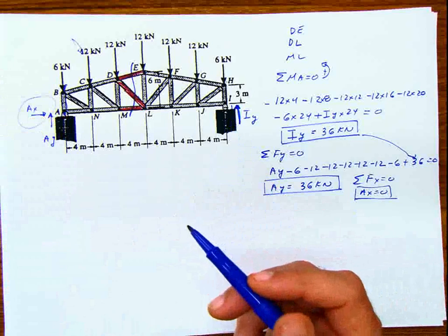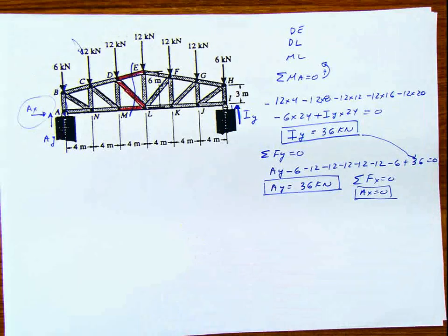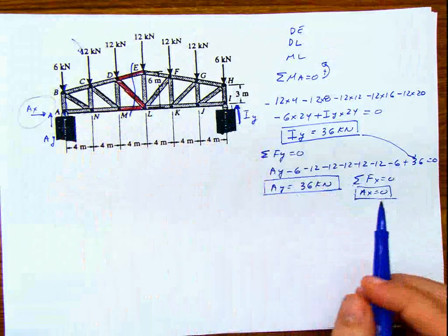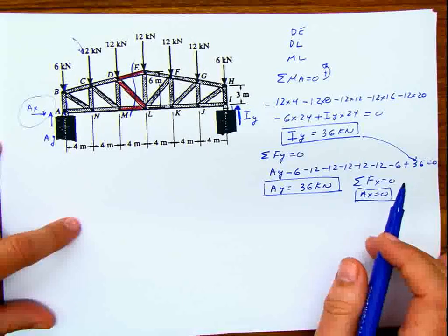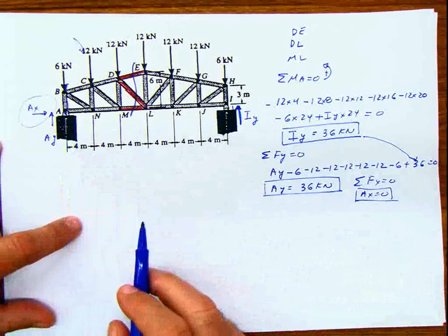So now imagine that you have just any type of element, any type of beam, and that beam is resting on 2 supports here. If I have one load only at the top of that beam, and that load is 100 pounds, this support is going to take 50, and this support is going to take 50. That makes sense. So when you have symmetry in the load and symmetry in the structure, like this one, this reaction and this reaction have to be the same.